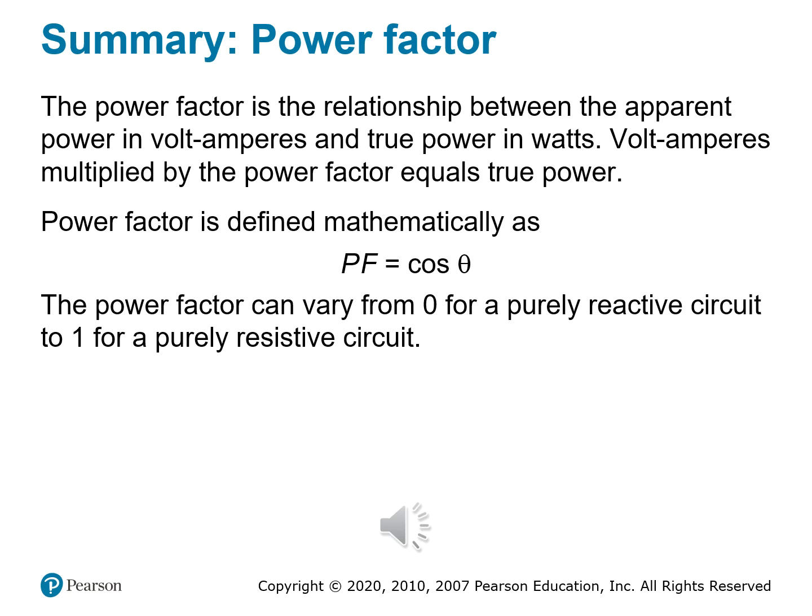You're like, oh, why should I care? Because lower power factor means more apparent power required for the same amount of real work. And that leads to larger components, higher currents, and wasted capacity in power systems. The same thing we mentioned before when we were doing RL systems. The general abstract understanding of this is the same.